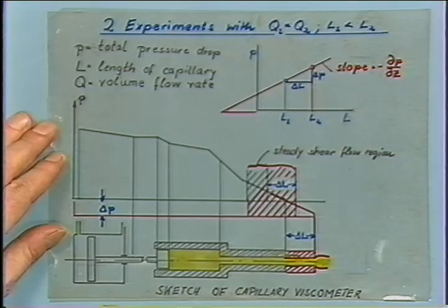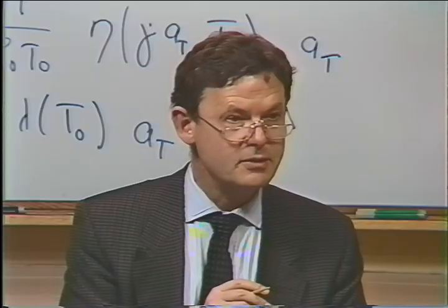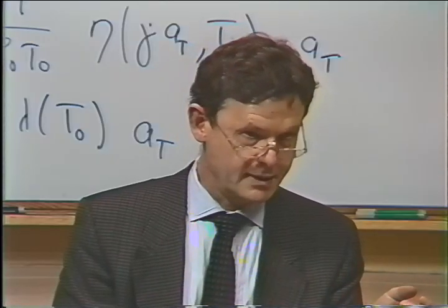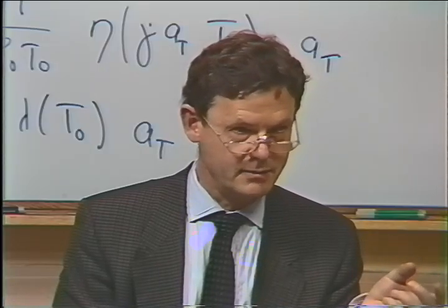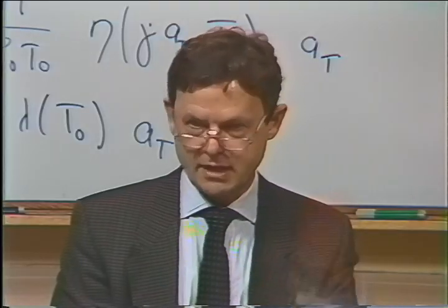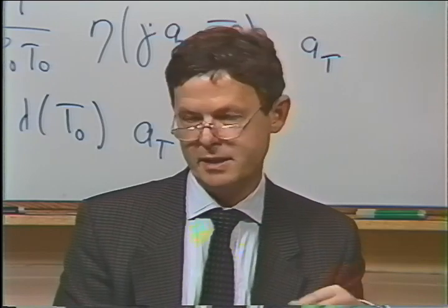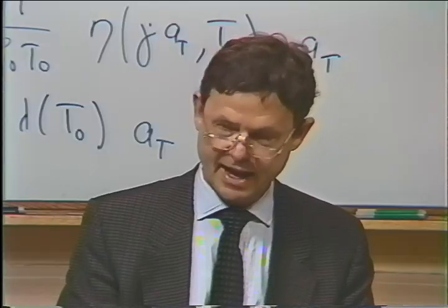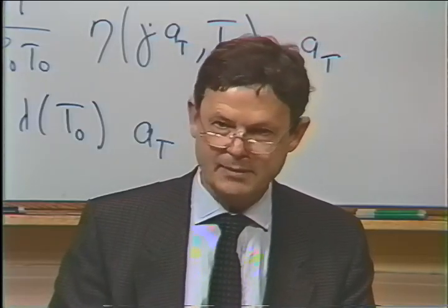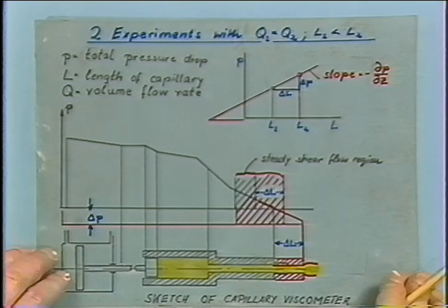Now, in the slit, we can measure directly. So we use one instrument to measure the pressure drop and divide it by the length and get the gradient. That's for the slit, available immediately. And for the capillary, you have to take off one capillary and put on a new capillary. Two capillaries are not good enough because of experimental error, so you want to do it with 3 or 4, and then you would draw this line here through the data points, and it's quite involved. So by using the slit, you save a lot of work. You get a lot of data in very few experiments.